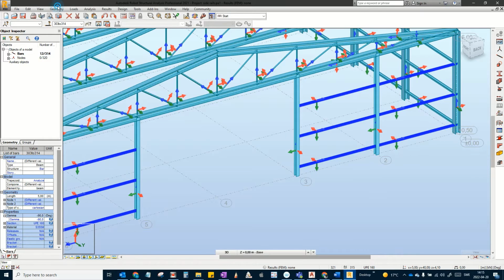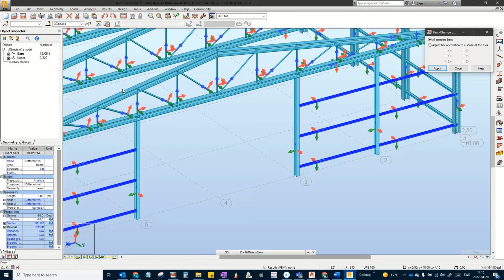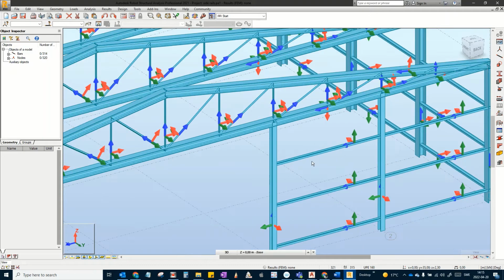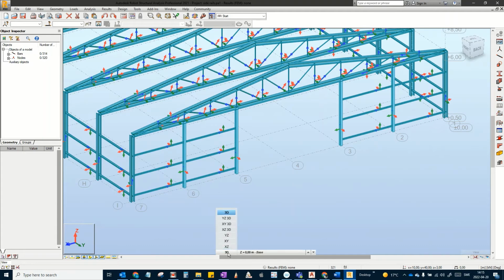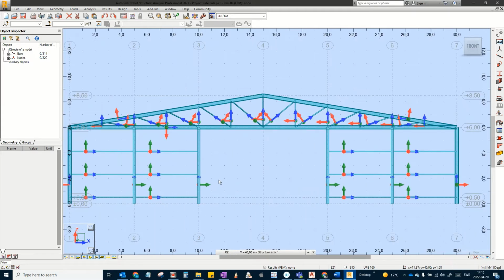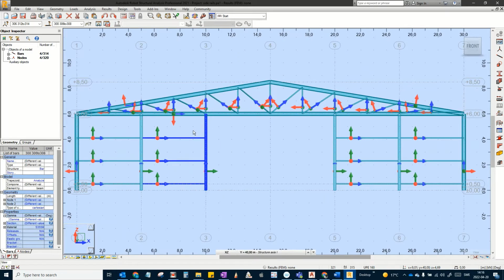Yes. Geometry is the option here, and local bar direction. So, okay, very good. It looks like we are going in the right way. So x theta again, but not in the 0, 0, but in the level 40 meters from there. We are going to create a column and beams here because we don't have support here.